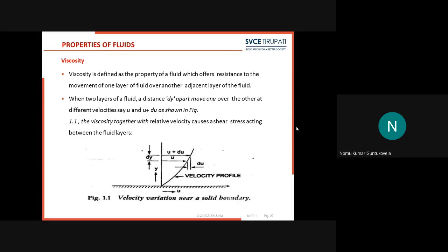When we take any surface and pour some water on it, whatever pressure we gave at the starting, by the ending position it will be zero, because the surface has the capability to resist the flow of the fluid. Instead of water, if we pour oil, it has a different specific gravity and a different viscosity. The general formula for viscosity is tau equals mu into du by dy.